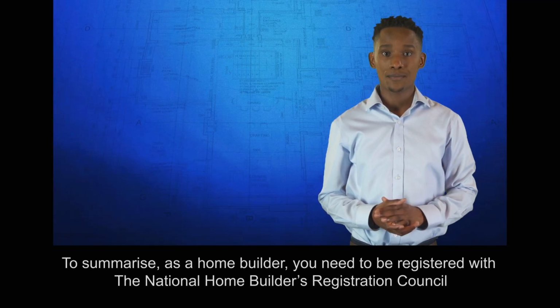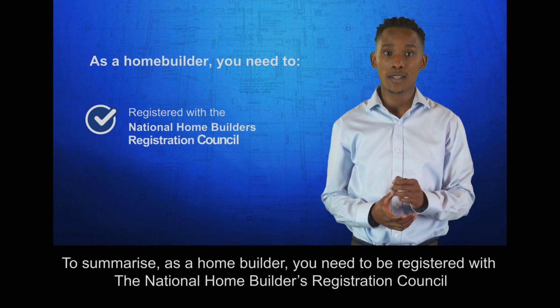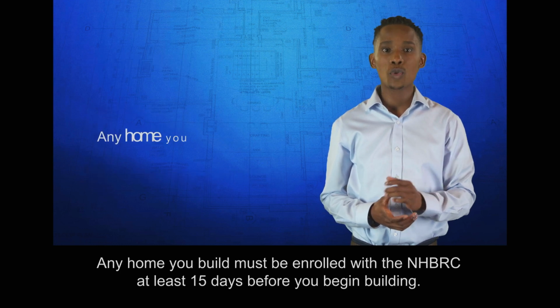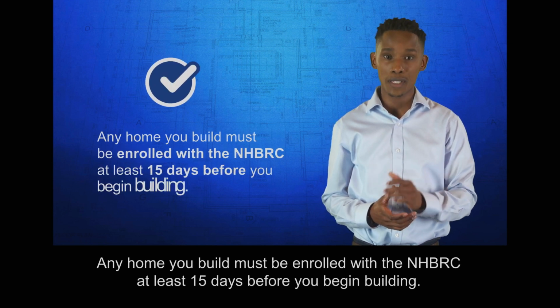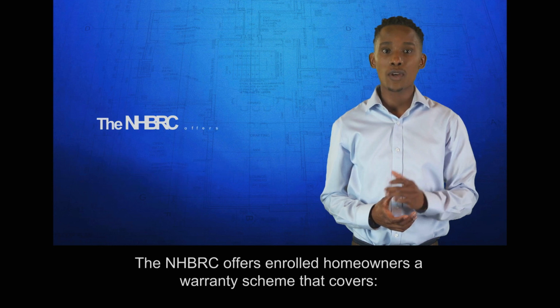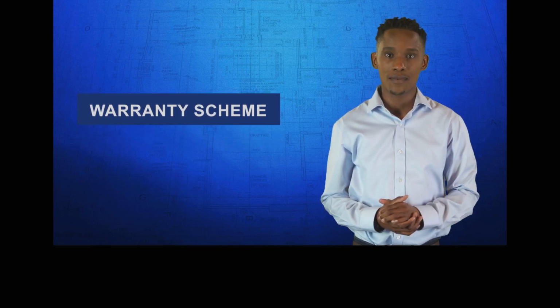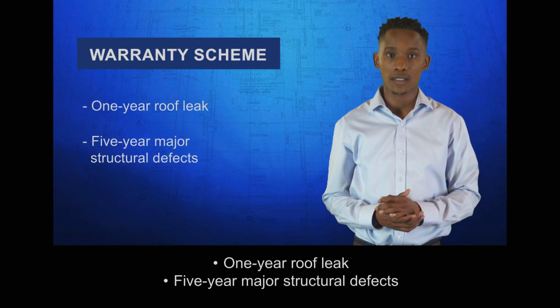To summarize, as a home builder, you need to be registered with the National Home Builders Registration Council and keep your registration current. Any home you build must be enrolled with the NHBRC at least 15 days before you begin building. The NHBRC offers enrolled homeowners a warranty scheme that covers 1-year roof leak, 5-year major structural defects.